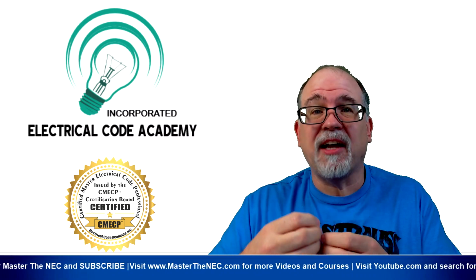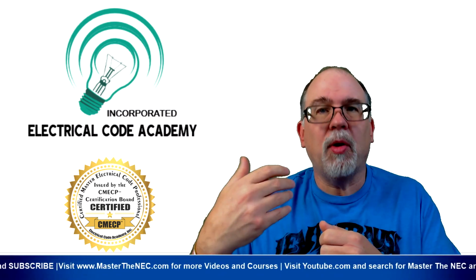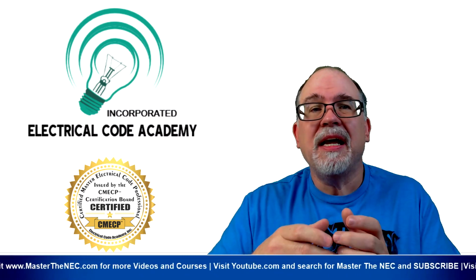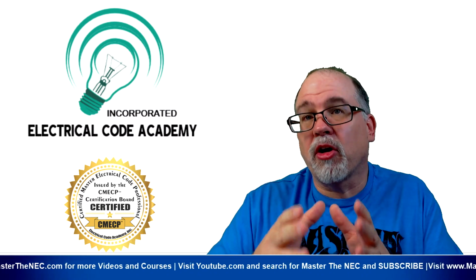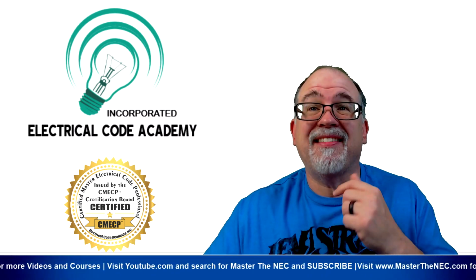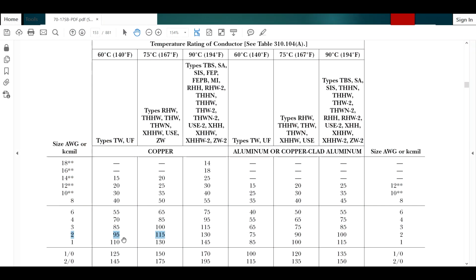But since my conductor has a higher temperature rating, I'm okay there. And because my terminals are 75, I'm okay there. So the limiting factor here is the terminals. That's why we're staying in the 75 degree column for our ampacity selection. So if that's the case, then we have a 2 gauge, and that's what we're dealing with.